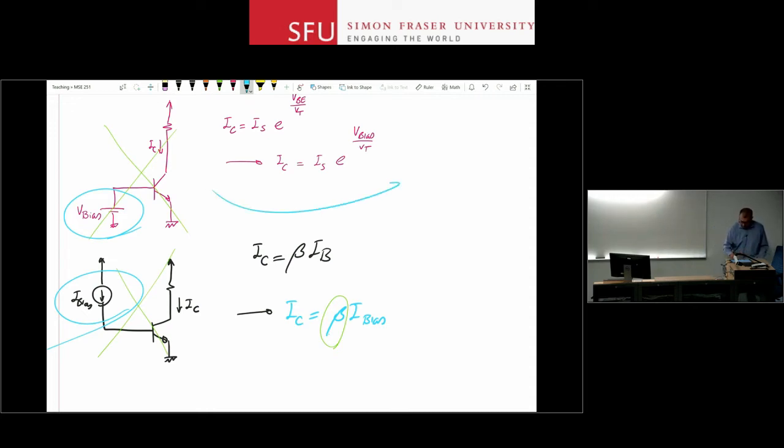So in this case, for example, what you do is you say, I have VCC to bias the device. I use a resistive voltage divider to get the voltage that I need here. So this voltage here is now going to be a function of RB1 and RB2. And if you choose it right, taking into account this IB here, you can, in theory, get whatever voltage you want at the base of that transistor and therefore bias it with whatever current that you want.